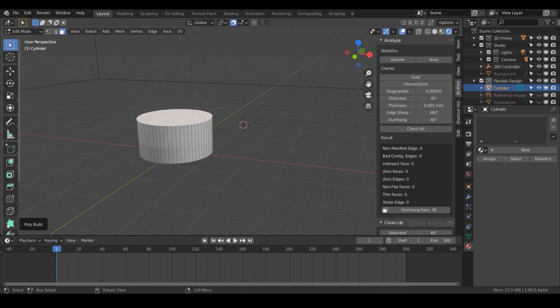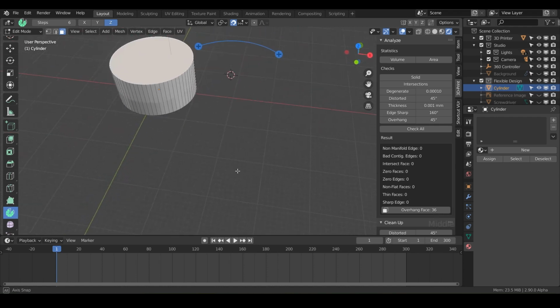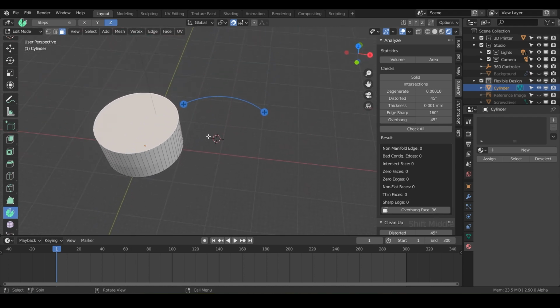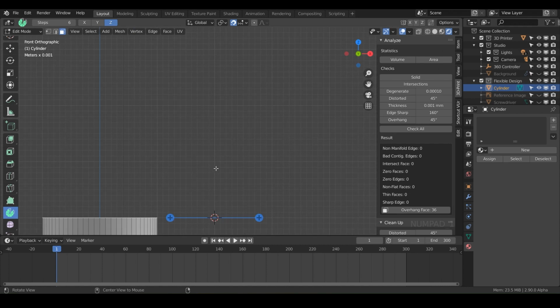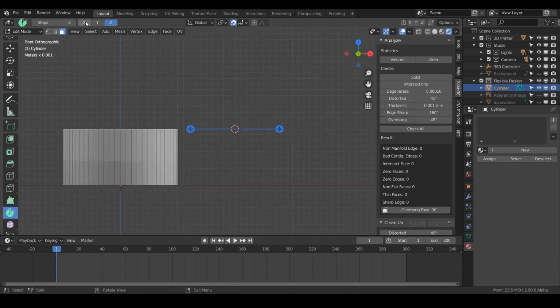And now let's do spin tool. So check this out. If you do spin tool, notice that the spin tool is playing off of the 3D cursor. So we're setting an anchor point, essentially. Go to our front view again with 1. And we want to add X and Y. So just hold Shift and click on these.